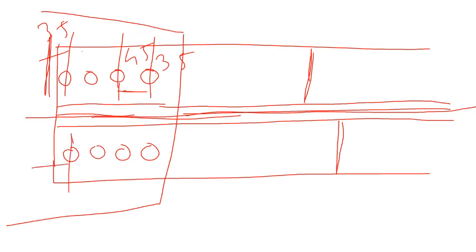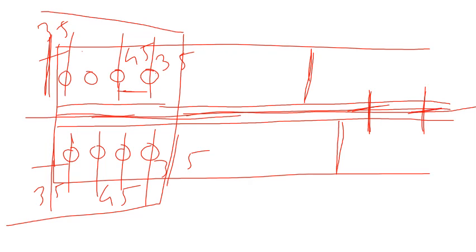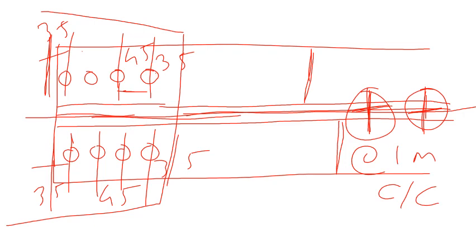So this will be again 35, and from here this should again be 35, and this distance is equal to 45. Tacking rivets will be there: this is the first tacking rivet, this will be the second tacking rivet, and so on. The distance between the centers of these tacking rivets will be 1 meter center to center. So we believe we have everything.